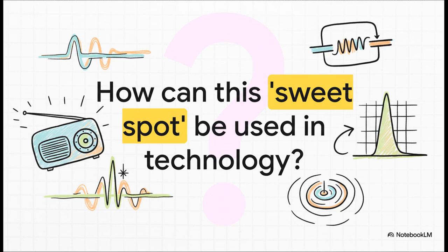When you turn that dial, what you're actually doing is changing the capacitance or the inductance inside that tuning circuit. You're adjusting its resonant frequency. You're literally hunting for that one sweet spot where the current from your favorite station signal is cranked to the max and every other signal just fades into the background.